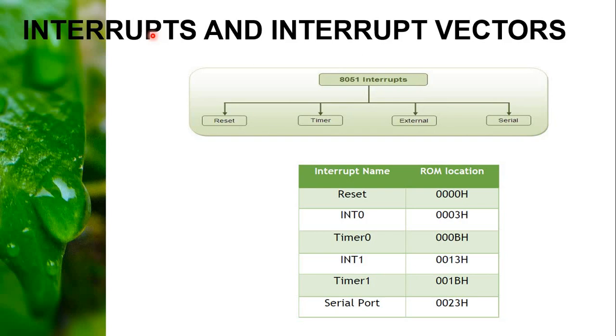Like that, the interrupt will perform. Now I hope you understand what an interrupt is. If the controller wants to complete a task immediately during an emergency condition, it needs to complete that first. So we hold off the main program, serve that urgent request immediately, and again continue with the same work we were doing. That is called an interrupt.